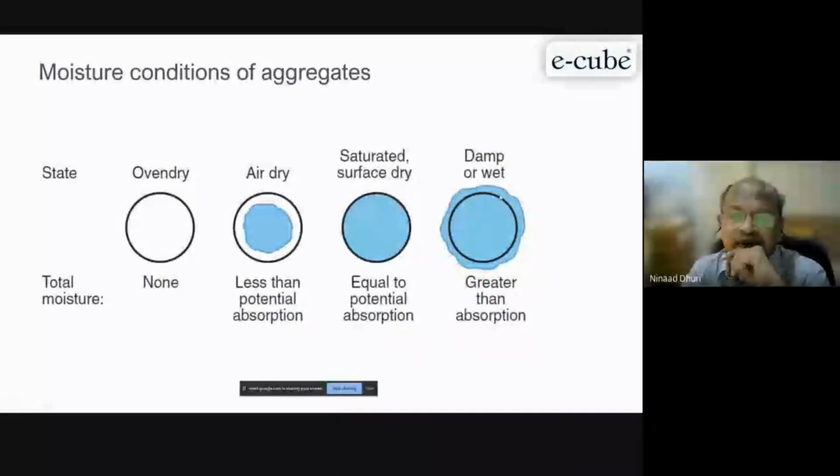Now, one point to remember is that whenever you are doing concrete mix design, all the calculations are based on this condition, SSD. Whatever mix design you receive from your laboratories or third party laboratories, all are based on this. That is what IS says. Some international methods go with the oven dry method also, but for convenience the IS standard goes with the saturated surface dry condition only.